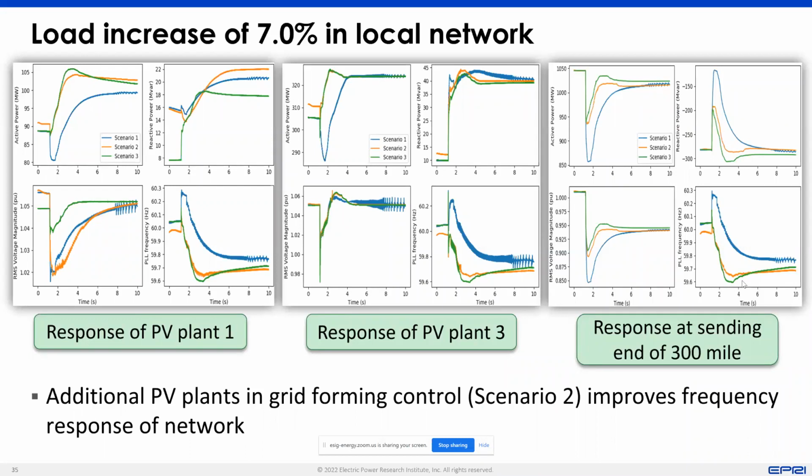Yes. One more comment. Since we talk about the added cost, if the scenario is that we only need to revise the control without the hardware inverter switching device upgrade, I think that cost should be manageable. I'm not from the manufacturer side, but I can imagine that changing the grid code can fit that. But like Nick said, if the change is a switching device upgrade from 1 per unit to 3 per unit or even higher, that's a different story.